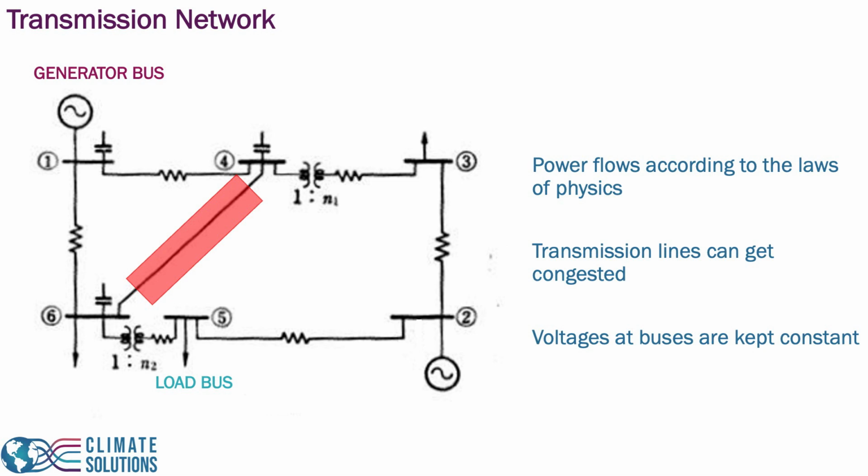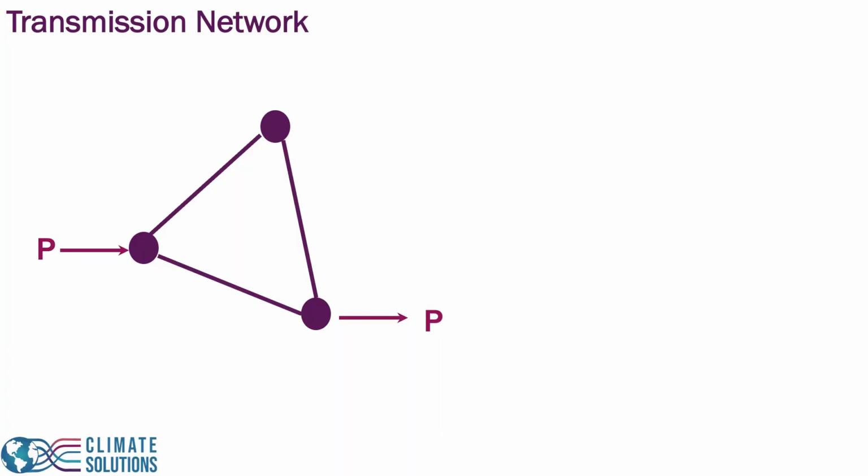One important issue on the physics of power flows in transmission networks is that congestion can be caused even when there's still line capacity left, because the flows of power are determined by the electrical properties of the lines. This is unlike, for example, highways, where the flow of cars can be guided through signals or advice so that cars and all the vehicles occupy as much capacity of the different highways as you need.